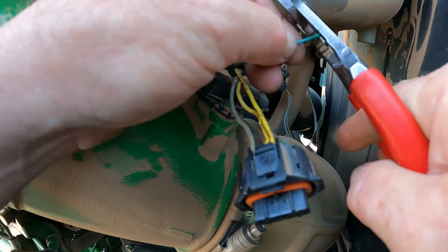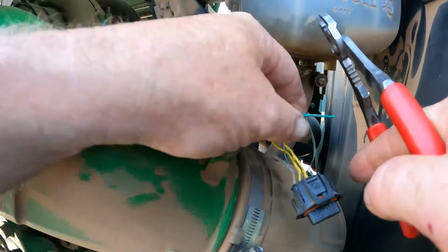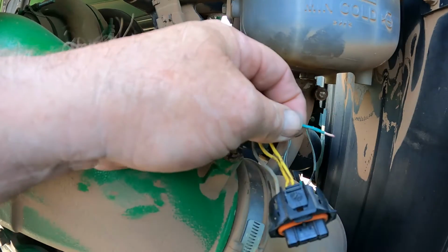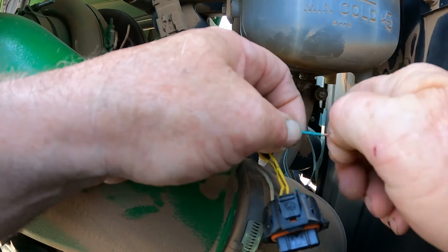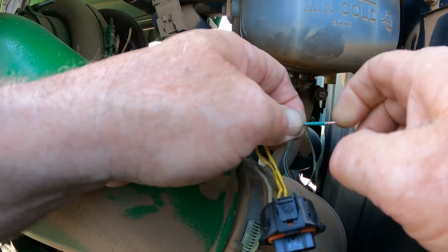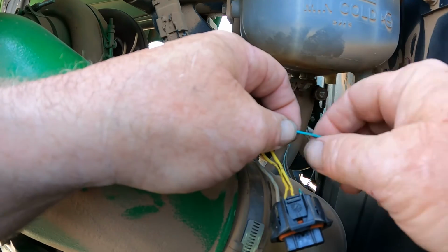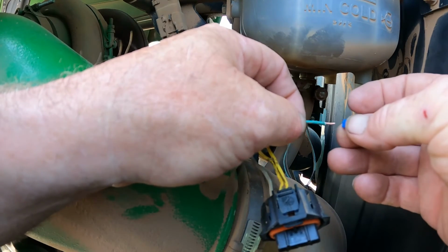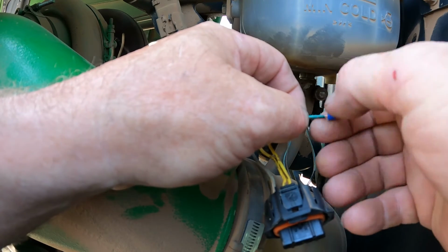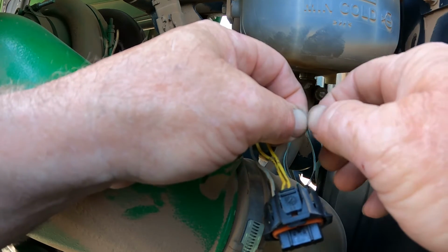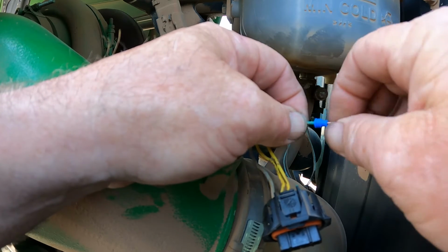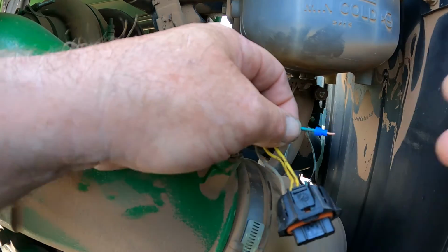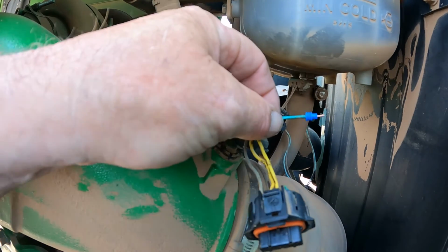So I'm going to go ahead and strip that coating on the wire back to get some good wire exposed there. So we've got good wire to crimp our new terminal on, okay? And I'm going to go ahead and stick my seal on there. Go ahead and run my seal up on my wire, okay, just past the exposed wire back to the coating that's on the wire, okay? So that's what that'll look like.